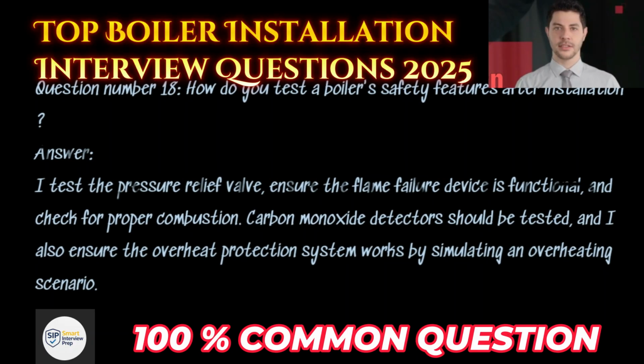Question number 18. How do you test a boiler's safety features after installation? Answer. I test the pressure relief valve, ensure the flame failure device is functional, and check for proper combustion. Carbon monoxide detectors should be tested, and I also ensure the overheat protection system works by simulating an overheating scenario.